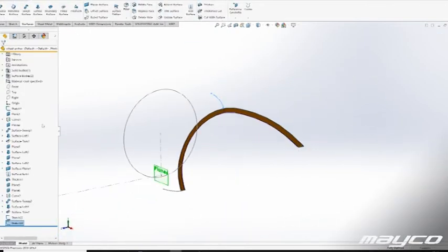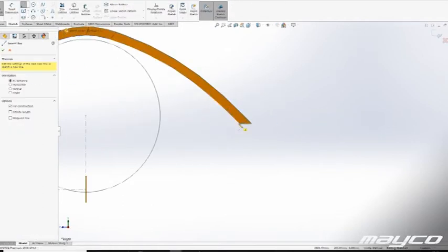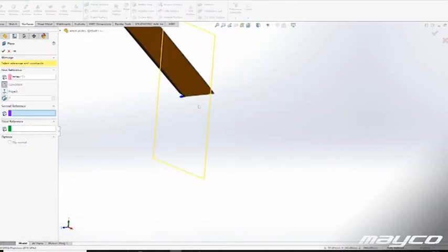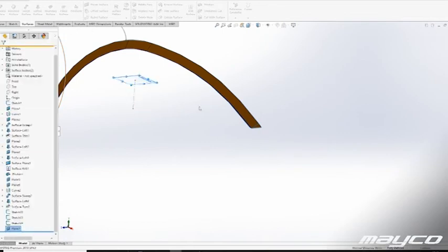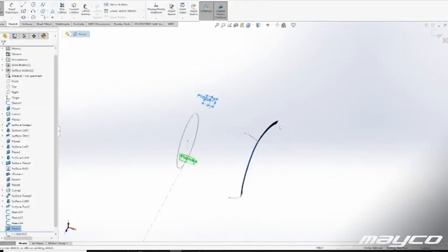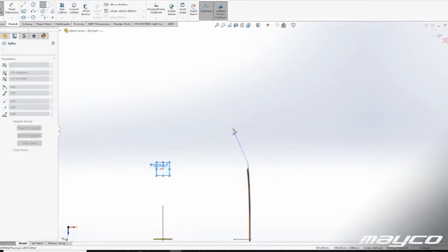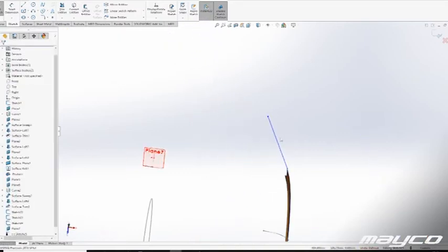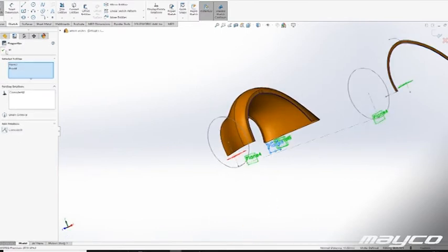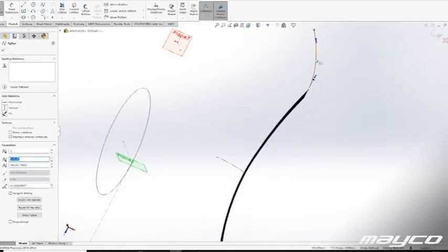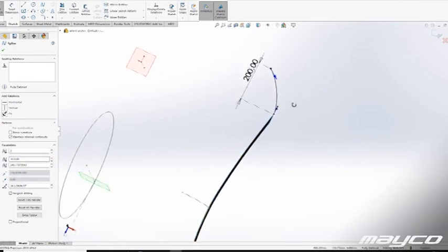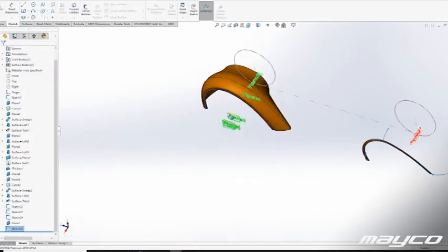Try to ensure that you have open shapes. Try always to have curves that you make in a certain direction, so either horizontal, vertical, or if you have a 3D sketch in the X, Y, Z direction, but try to have curves that are open and do not cross into each other, for example. And also what sometimes happens is that you make a surface and it doesn't really understand what it's supposed to do, and then it bows out at a certain point, and it's very difficult to see sometimes, but when it happens, that's where the surface will fail.